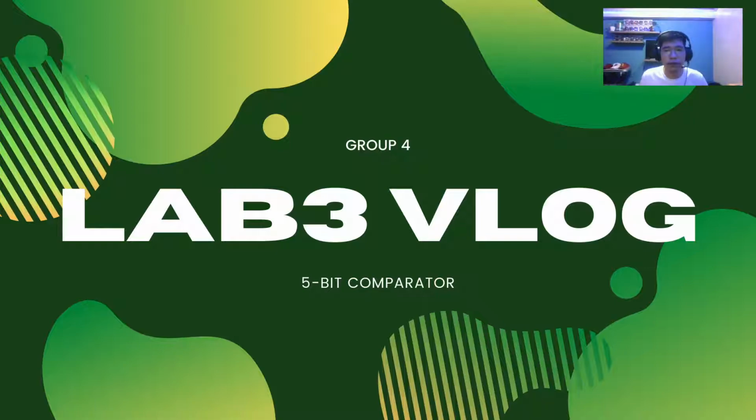For our LAB3 vlog, I'll be creating a 5-bit comparator. Before that, let's discuss what a comparator is. A comparator is something you use to determine the relative magnitudes of two binary numbers. It compares two n-bit binary numbers and produces three possible results at the outputs. Comparators are combinational logic circuits that are used to test whether word A is less than, equal, or greater than word B.